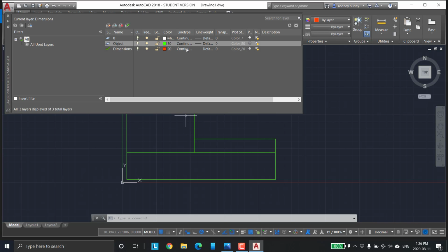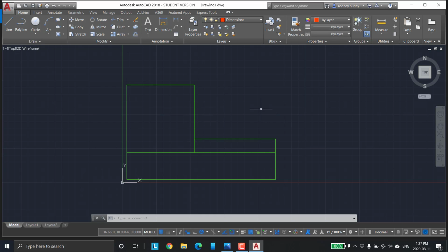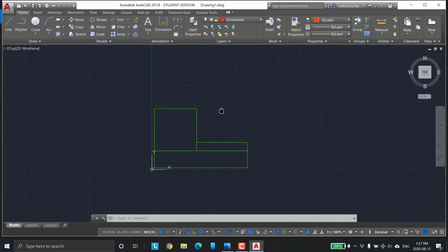And again, you can change the line types to heavy. Typically when we're drawing, the object line is thicker than it is with the dimensions, but we'll go over that afterwards. I'm not really concerned with that right now. So we're going to exit out of that for a second, and we know now we're drawing on that particular layer. Okay, so now we're going to go dimensions.